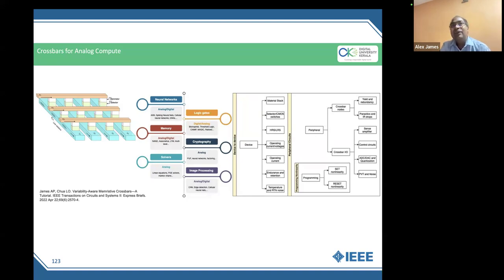Should I address those errors at the device level, remove all the possible variabilities and make a perfect device? Or should I go about it at an architecture level, working around it, compensating for it? I can put compensation circuits and other things to reduce that. Or do I think about an architecture which would automatically compensate for that?